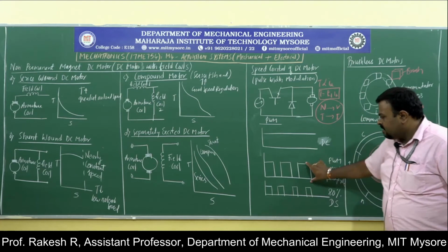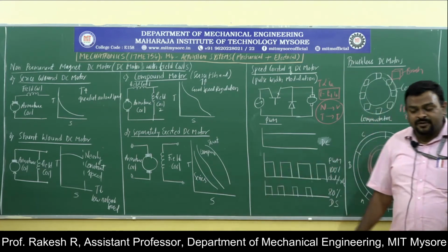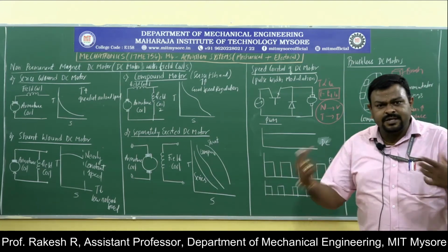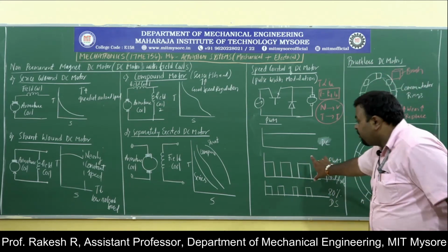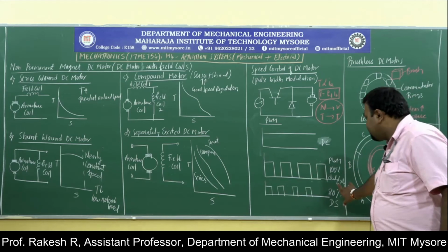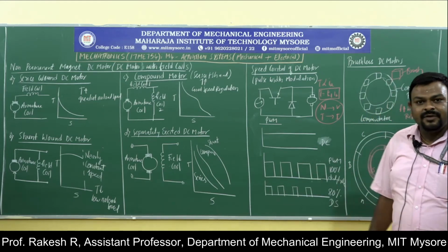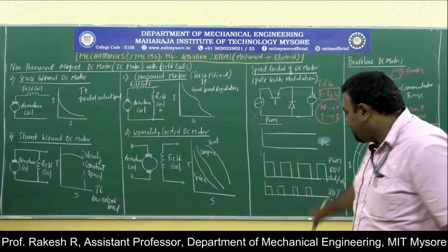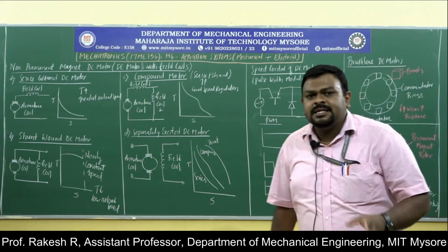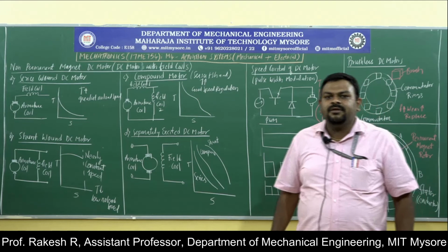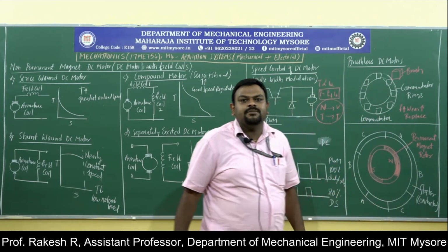And here, this is 100% output you are using. That is nothing but if you are using all, it is 100% duty cycle. If you are using 50 RPM here at 80%, 50 into 0.8, you are using 40 RPM. So 80% duty cycle. You can use a DC like an analog signal. That is one of the advantages of pulse width modulation.